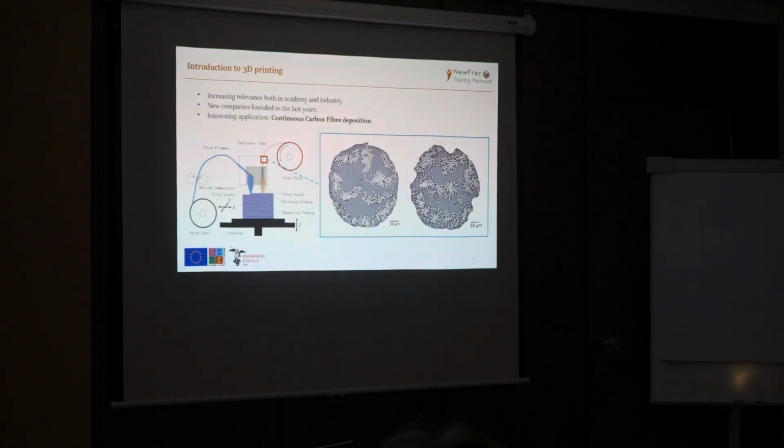But I just wanted to stress this point in order to maybe find a solution to this problem, because using a length scale which is lower than the diameter of the bundle, we don't get exact results, but we get something which is considered physical. While if we use a length scale which is wider than the carbon fiber bundle itself, we get more accurate results in terms of residual strength and strain failure, but we wanted not to use a length scale which was higher than the fiber bundle itself. That's the main reason. So you are considering it to be a numerical parameter.